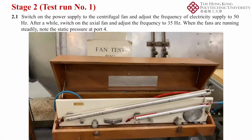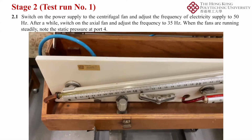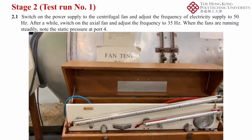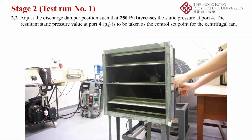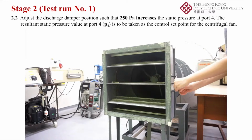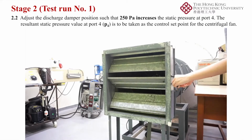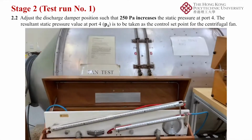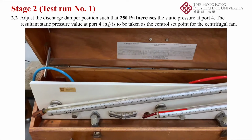When the fans are running steadily, note the static pressure at port 4. Then, adjust the discharge damper position such that it increases the static pressure at port 4 by 250 Pa. The resultant static pressure value at port 4 is to be taken as the control set point for the centrifugal fan.